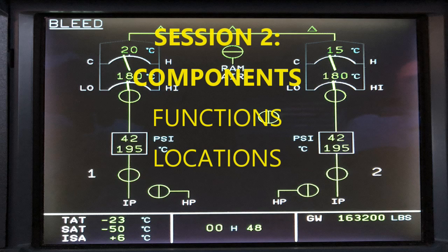Okay. Now, when does it close? When does the pressure regulating valve close? Okay, remember it's regulating the temperature. We want to make sure the temperature is not too high. So it's going to close if there's an over temperature downstream. Remember, I mentioned the Precooler exchanger earlier, and the cooling using the fan air valve and the thermostats there to monitor that.